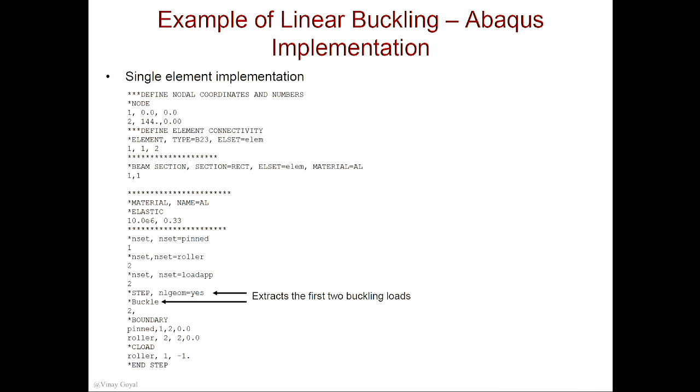So for example, let's say that the buckling load is 1,000 pounds. If I apply a value of 1, the eigenvalue I'll get from Abaqus is 1,000. If I put a value of 10 here, then the eigenvalue Abaqus will give me is 100. If I put 1,000 here, then Abaqus will say the eigenvalue is 1. Now say I put 10,000, then the eigenvalue in Abaqus will be 0.1, and 0.1 times 10,000 gives you a value of 1,000, because the buckling load is 1,000. So no matter what, the eigenvalue that Abaqus gives you times this reference value, those two together give you the buckling load for that beam. Is that clear?